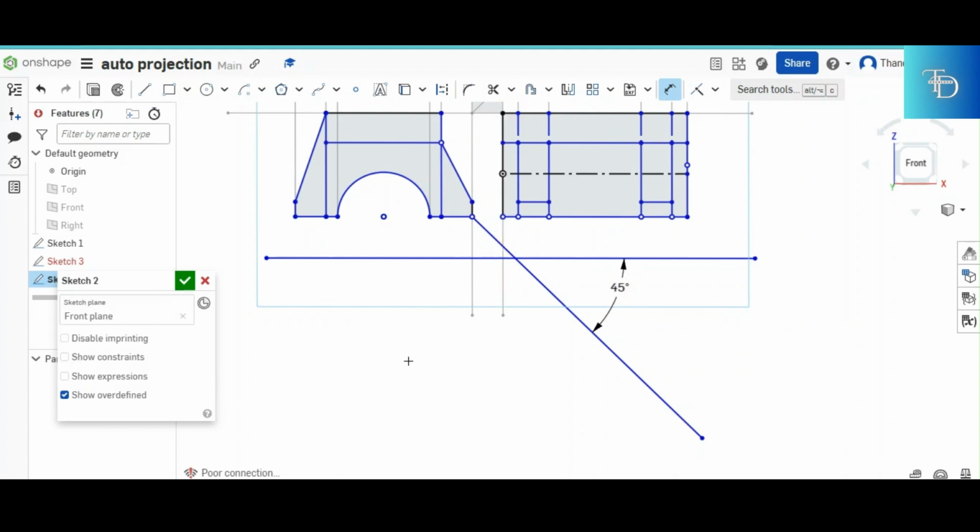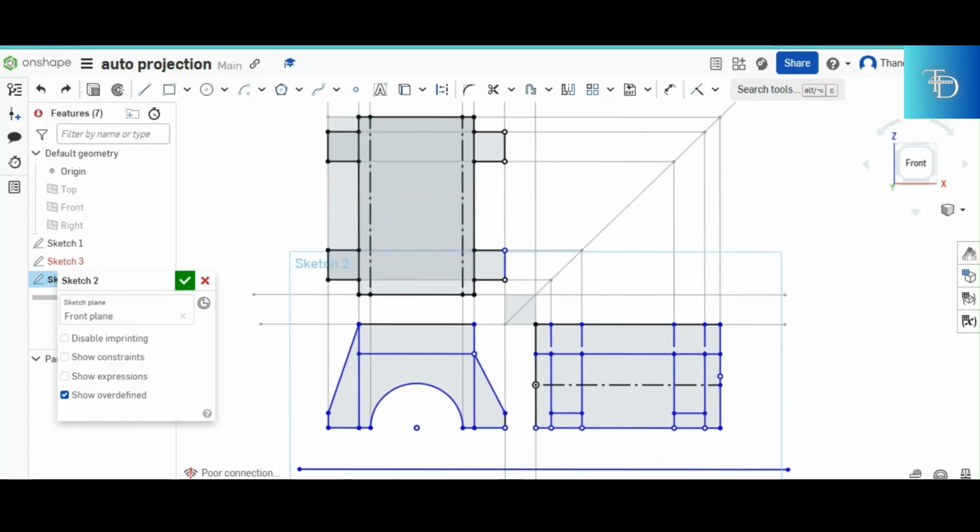Because that is where it would be stationed if this was in first angle orthographic projection, but now it's in third. Since it's in third angle orthographic projection, it's going to be like this. So ladies and gentlemen, this is how you deal with first angle or third angle orthographic projection. Given the isometric view, you know how to peel the parts from an isometric view. And where they try to complicate things and give you two views and one missing view, you have to apply the skills that I've just shown you here.